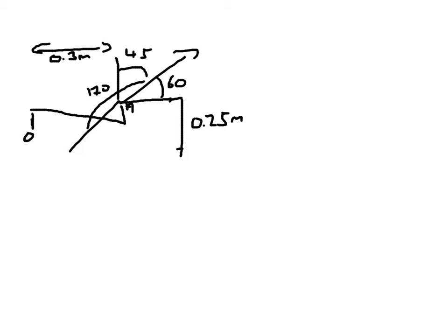So we can start to solve the moment, both the moment about the point O, but also how much that turning effect is about the x-axis. Because if you imagine your x-axis is down here, how much of that turning effect that's being applied by your force is actually trying to pull the whole handle and turn it around the x-axis. So turn everything that way. It will be that way because it's lifting it, so that way about the x-axis.